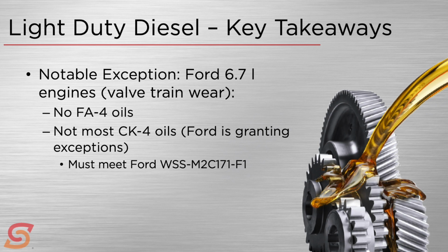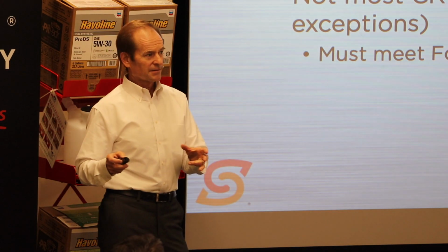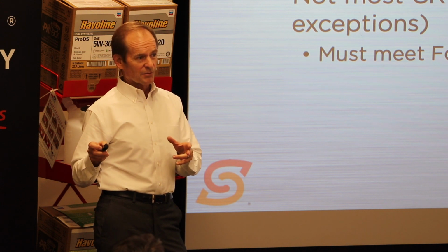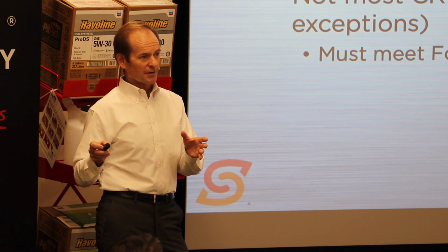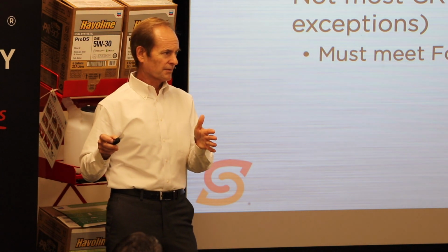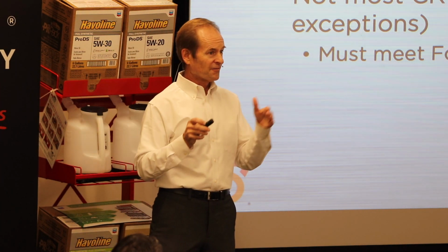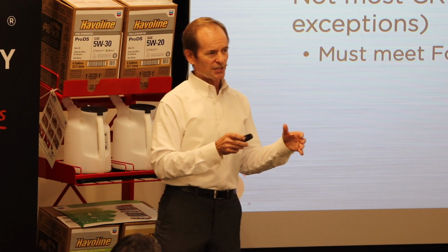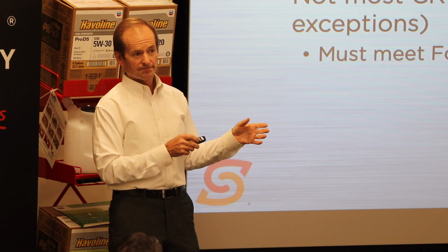Ironically enough, on the light duty side, within the past couple of months or so, Ford came out with a bulletin announcement that they're going to allow or want or specify FA4 oils, the light stuff, for use in their diesels that they're putting in their F-150s.